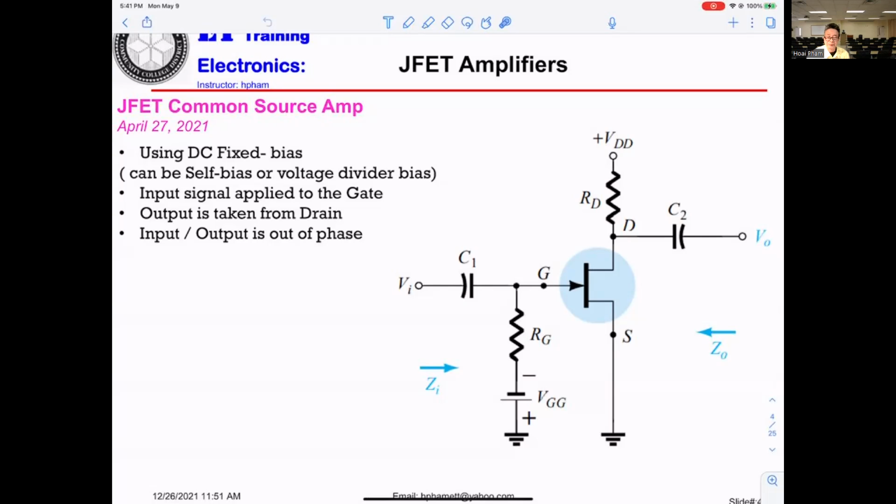Also, make sure you understand the voltage VGG and the VG will be the same. If you get minus 2 volts here, VG is also minus 2 volts here. How? You get a resistor RG here with a very high value, so the current cannot flow through it.